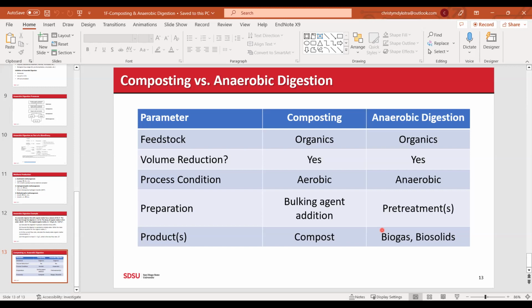So that's really important. The other thing that's important is if we were introducing air through a blower, we would have to figure out how much oxygen is needed. Based on the fact that we have 21% O2 in our air, we could figure out, for a certain amount of waste, how much air would need to be pumped in to satisfy this oxygen demand and produce the compost.